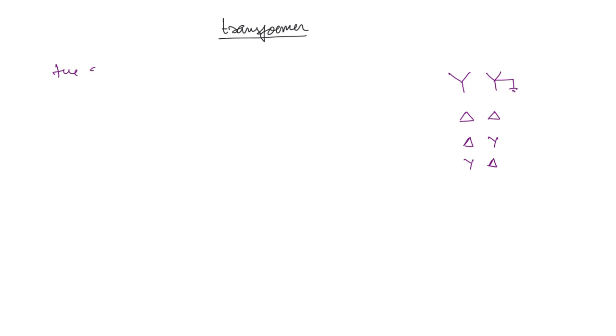The positive and negative sequence network is simply going to consist of one impedance. It can be Z1, which is the positive sequence impedance, same as the negative sequence impedance. Both of them are equal. Now we will see the zero sequence networks.